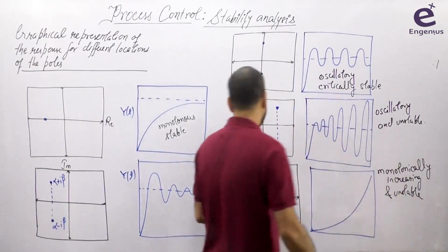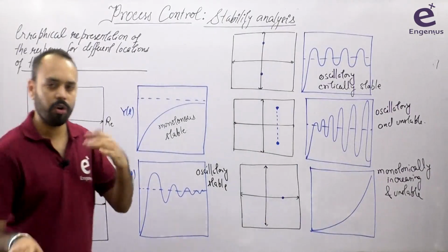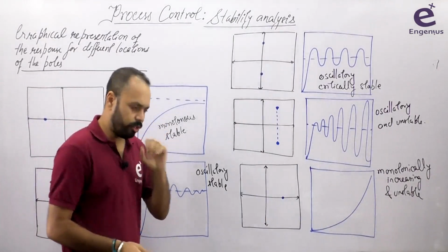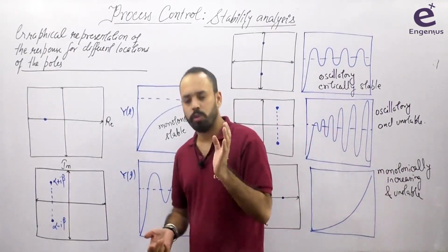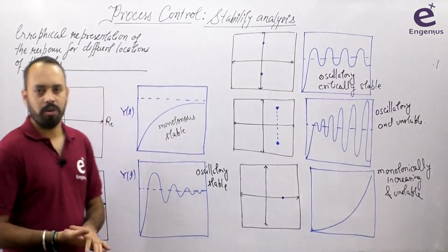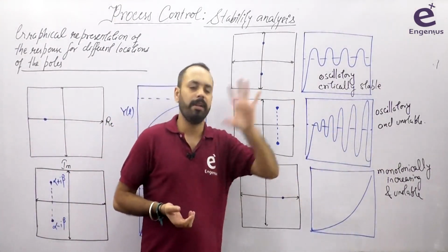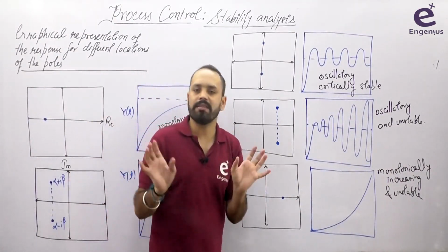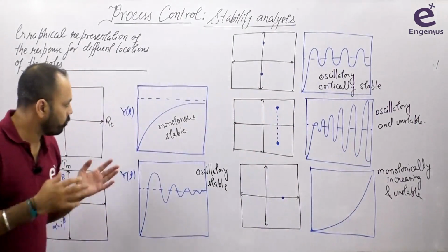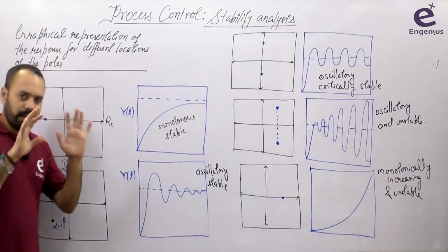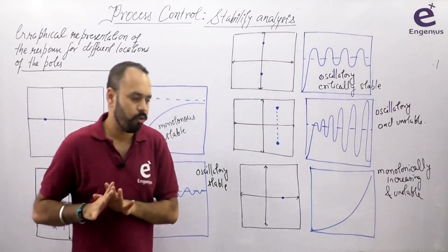This is some more understanding of stability. तो देखो एक चीज ध्यान रखना, the response being oscillatory or non-oscillatory is decided by whether the roots are real or imaginary. Fine. The response being stable or unstable is decided by whether the real part is negative or positive. So you can have oscillatory and still stable, and you can have non-oscillatory and still unstable. तो stability का oscillation से कोई लेना देना नहीं है. Stability has nothing to do with oscillations. Oscillations are a completely different thing. Stability is a completely different thing. So you can see yourself what the various possible cases are, right? So in this lecture, I have discussed everything about which response should be called a stable response. Fine. So I also gave you conclusions.